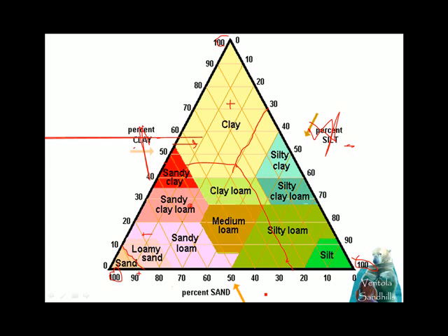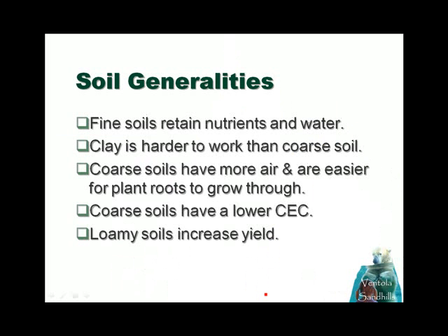So this slide just lists some generalities. Fine soils are going to retain nutrients and water more. Clay is harder to work, to move. Friability, we call that, the ability for equipment, plows to get through it.